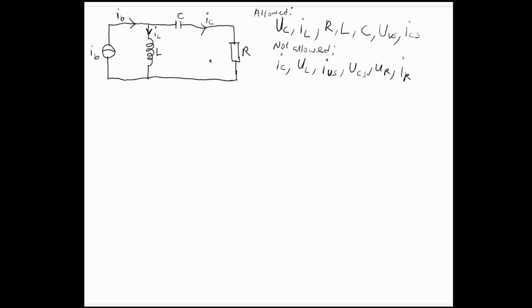Therefore, we are going to have two differential equations. So you pick any one you want to start with. And by the way, I'm not even concerned with voltages at each node because for me personally, the voltage across an element is sufficient. This is ground, already. I know that is zero. This is the reference. The voltage across the inductor is the same voltage as on the node at this point here. So there's no need to account for that.